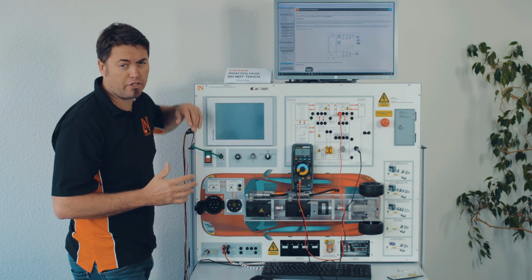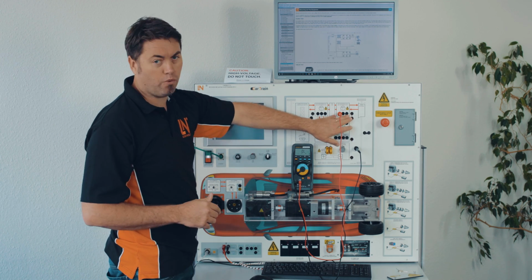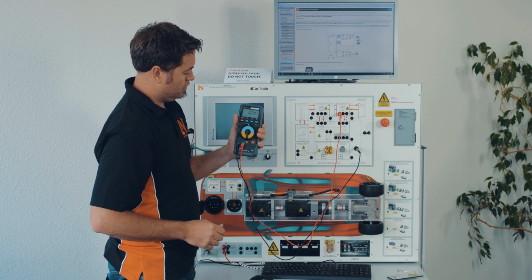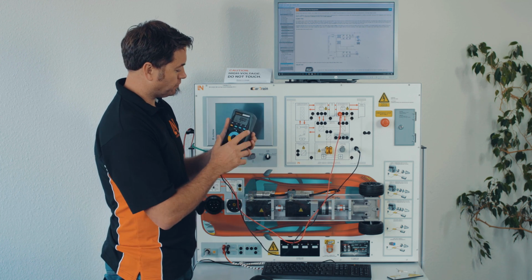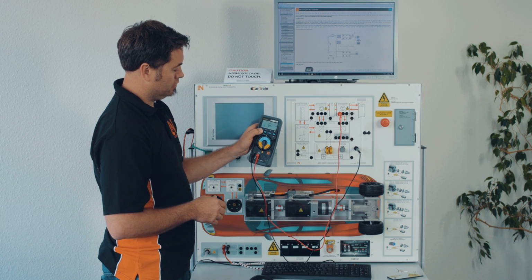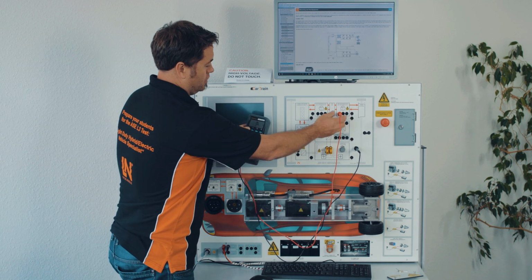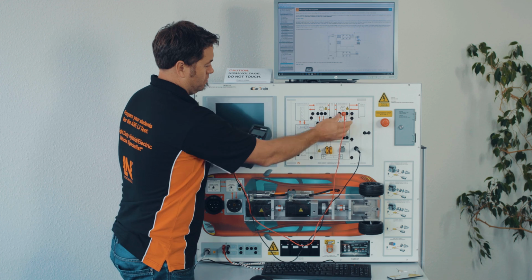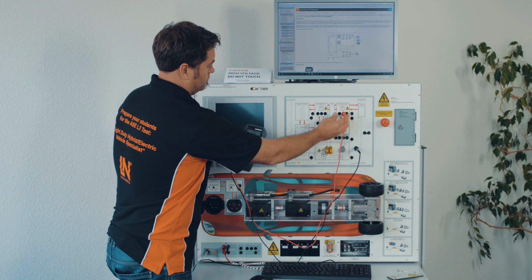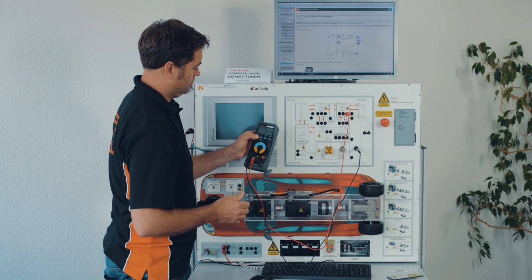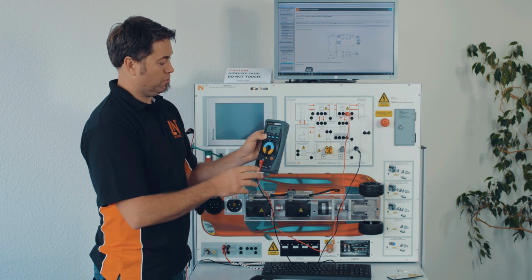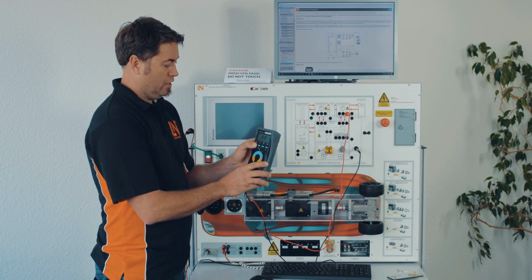And nothing, no change, I can't see anything, but I know there's a fault within this system. So what I need to do here is I can change that to 1 kV. And when I press test here, now we're actually putting 1000 volts into the system. You see now, we've got the system come up that's found that leak.